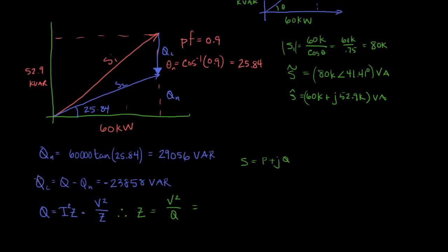So when we're looking at this equation here, you don't want to put the J in there because it'll in fact give you a completely wrong sign answer, because when you have the J in here, it becomes a negative and the negatives cancel out, and that wouldn't make sense, right? Because we know that the impedance of a capacitor should be a negative value.